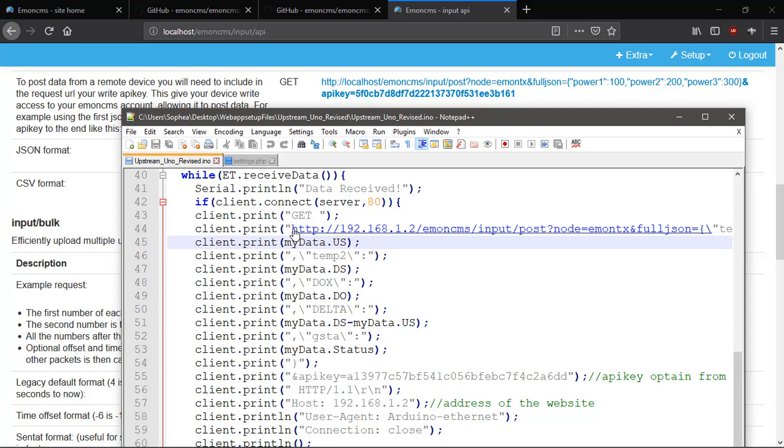So you should be using a static IP address. By static IP address, I mean the IP address that does not change every time you connect to the network. It should be the static IP address. So if every time you connect to the network and your IP is different, it means that you cannot use the web application, because from Arduino program we cannot change the IP address every time. So if we connect to the network every time and the IP address still changing, it means we still upload our Arduino code every time. So we need to assign the static IP address to our web hosting application.